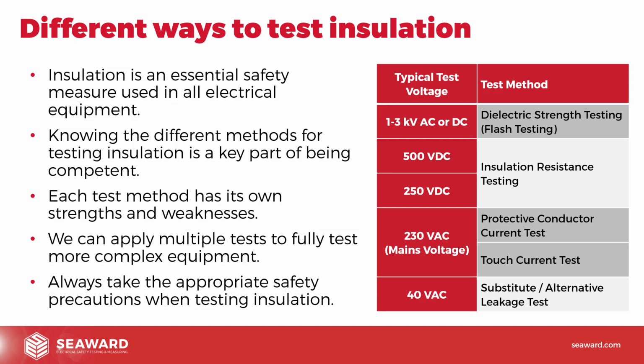So there's also, as I've mentioned in the bullet points there, safety considerations to be taken into account. If we're going to apply thousands of volts to this piece of equipment, that's potentially dangerous for the tester. So the person doing the testing, that is. So we need to take safety precautions. We need to have a proper safe test area set up. We need to have insulated mats. We need to have barriers. We need to have all of these things set up to be able to do that. So it isn't necessarily something that you can just do in somebody's office, say, or a workshop. You'd have to have a designated test area set up for doing that.